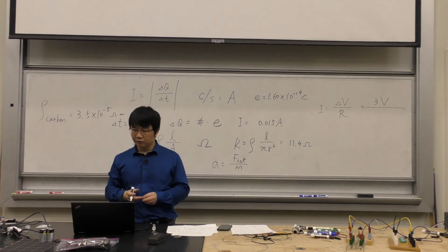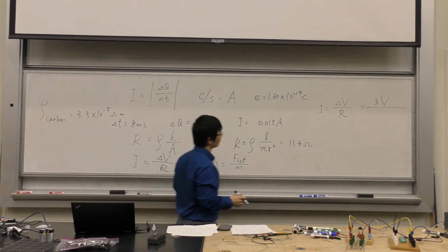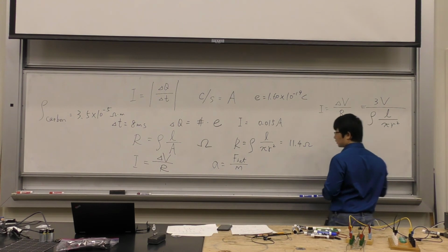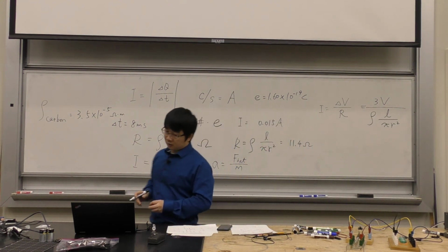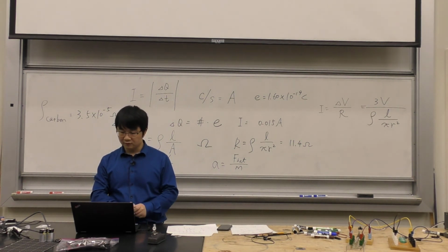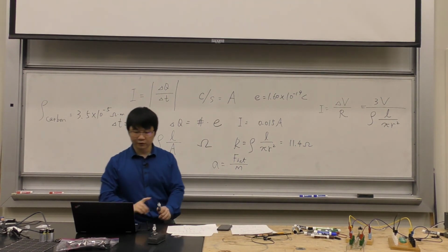Then you need to find the resistance. Well, the resistance, you can use this equation. It's still going to be rho length over pi r squared. The length is given, the radius is given, so you don't need to divide it by 2. Convert everything to SI units. Look up and find the resistivity of copper.